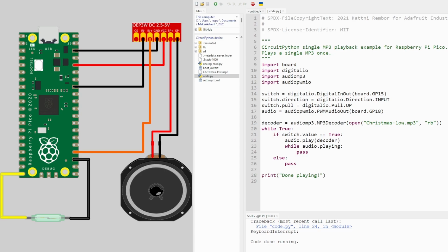Moving down, the next black wire is another ground, and that is on the input minus input ground of the amplifier. It's only a mono file that I'm playing, so I don't need to have stereo sound, so I'll just ground one of the pins. So I chose to ground the negative, the in minus.